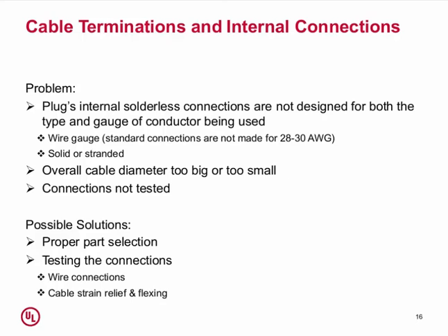Again, when you get into category 6 and 6A cabling, the traditional approach of squeezing the cable, putting a dent in it to make sure that strain relief is going to hold properly, is not the best approach. You really want to put more even pressure around the cable to maintain the geometry. And if the cable's not sized properly for the plug, or the plug's not sized properly for the cabling, I'm going to have slippage and eventual connection failures.